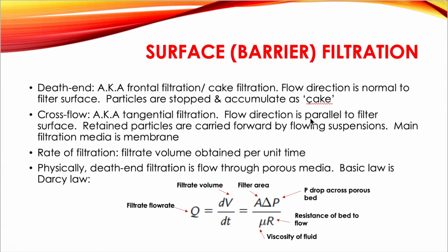For surface or barrier filtration, the first type is dead end and the second type is cross flow. Dead end, also known as frontal filtration or cake filtration, is when we have a flow direction normal to the filter surface. So this is the flow direction, for example, and you have your filter media here.